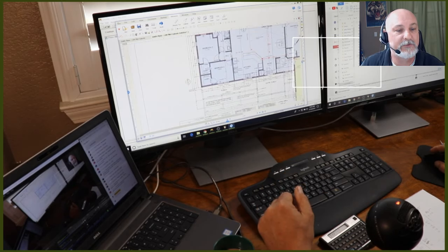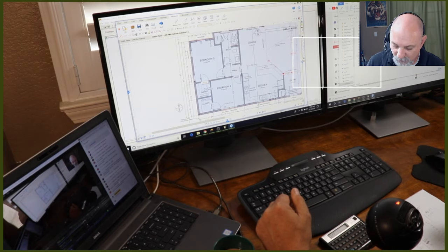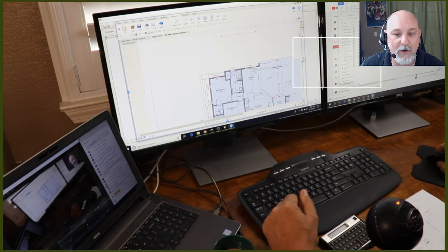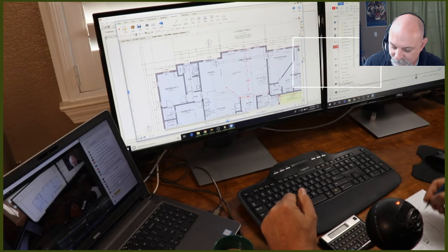So let's go to our left wall. I only have 2 windows on the left face, and both of those are 2040, so 8 square feet apiece. Our back wall, we've got a few windows and doors across the back that we need to account for. A 305 window, that's 15 square feet.